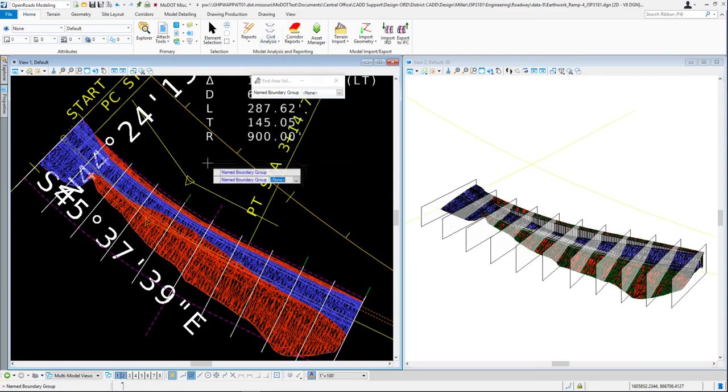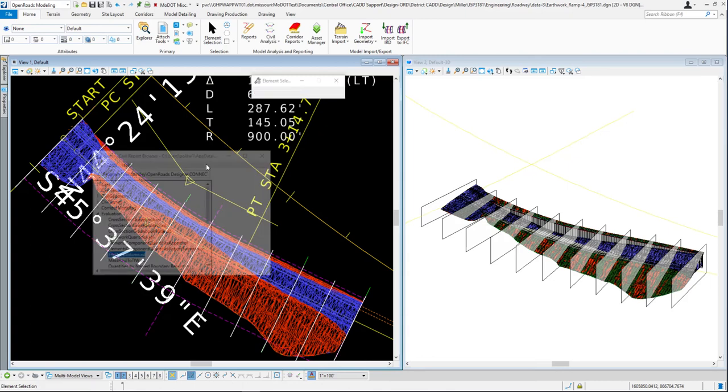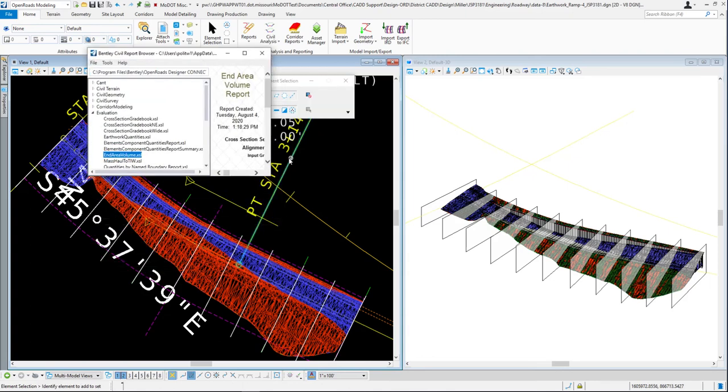Right now, it's set to none. I'm going to hit my arrows to choose my option of ramp 4. Go ahead and select in a blank area. And then the next part of this is you can select to remove shapes that you don't want to calculate. Or if you've got everything in there that you want, you can simply reset or right click to advance the tool. So we'll go ahead and right click. It's going to go out and create this XML report.